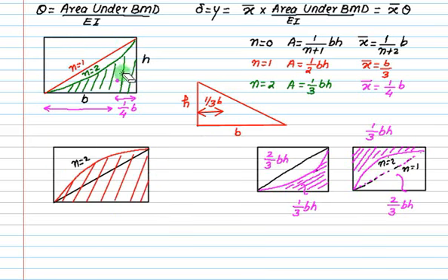This figure is called a spandrel. This is not a spandrel. The generalized equations are only applicable for a spandrel. If you want to write down the centroid for this one, mark the centroid somewhere here. Always mark your distance from the height side of a triangle. Is this the height H?